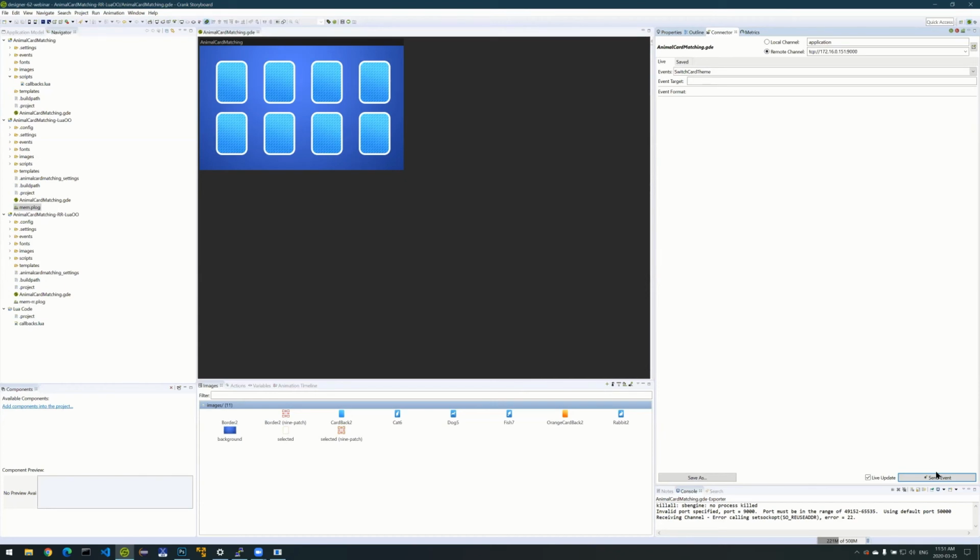Well, this way you can test your UI by sending the events that you would receive from the back end, and make sure that your side of it is okay, that the UI side performs and reacts the way it's supposed to when it gets the events that it's going to receive from the back end when the back end is eventually designed. So you're decoupling the back end development from the front end UI, and you can still simulate it, test it, and validate it on the hardware remotely through Storyboard IO over a TCP/IP connection.